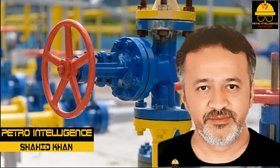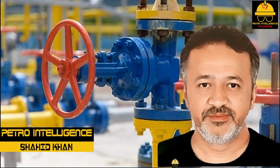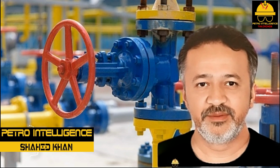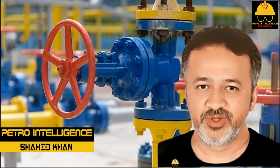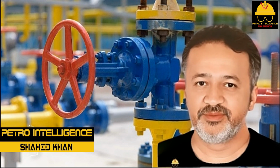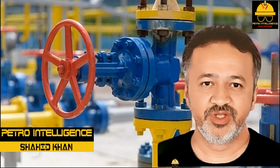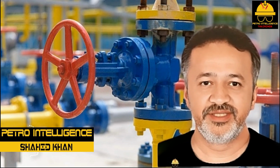Gate valves. One of the more common valves found in industry is a gate valve. A gate valve places a movable metal gate in the path of a process flow in a pipeline. The gates are sized to fit the inside diameter of a pipe, so very little restriction occurs when it is in the open position. Valves vary in size from 0.125 inches to several feet. Gate valves typically are operated in the wide open or completely shut position. This type of valve is used where flow rates are not restricted.